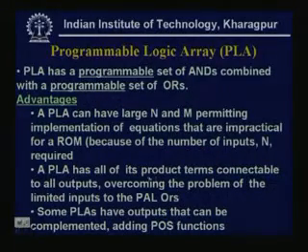Now, a PLA has all of its product terms connectable to all outputs, overcoming the problem of the limited inputs to the PAL ORs. The same min term can be used by more than one function.